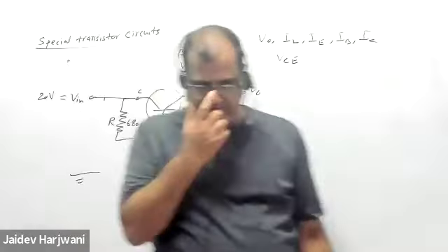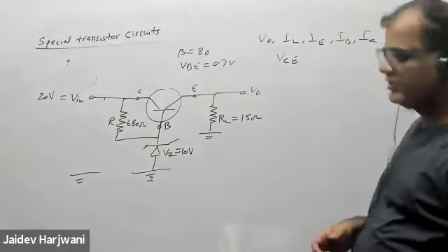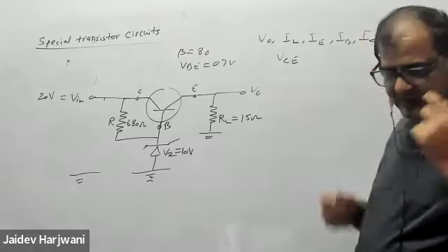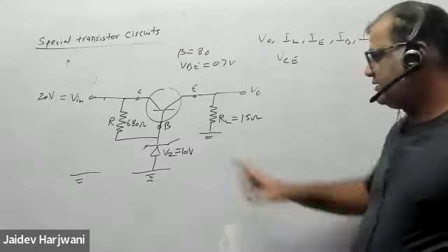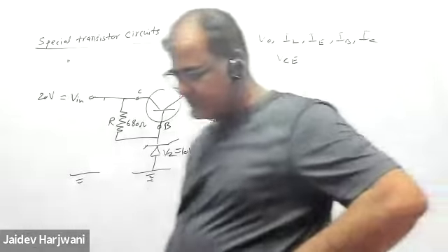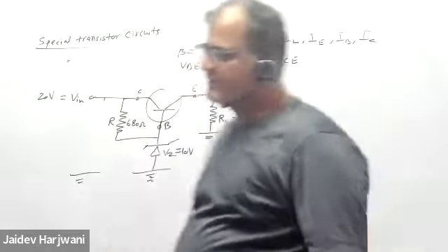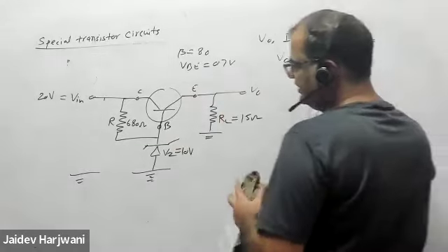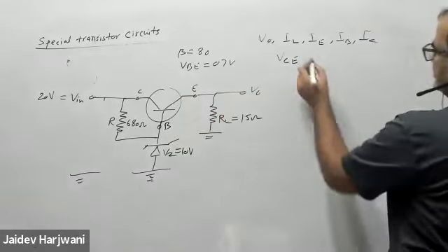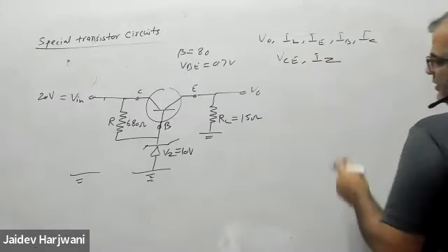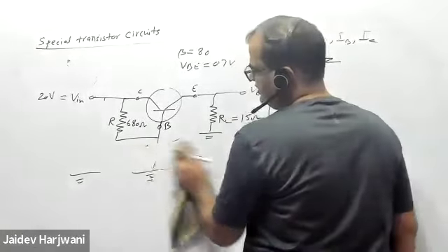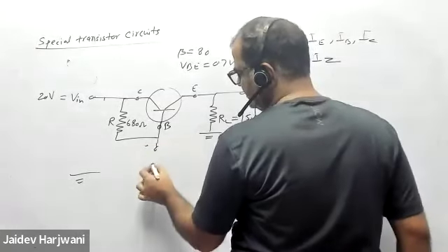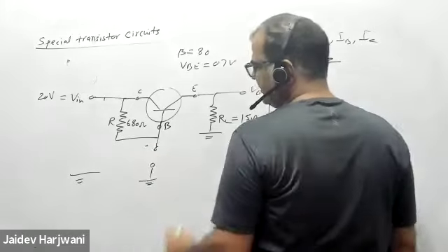Now, what is the first job? What do you have to find first? The open circuit voltage across the Zener diode. First, you have to check whether the Zener is on or not. If it is on, then things become very simple and you can directly calculate everything. You also have to calculate the Zener current, IZ. For the moment, first I'm checking. This is not a part of the solution, this is just for checking. I'm saying this is off, an open circuit.